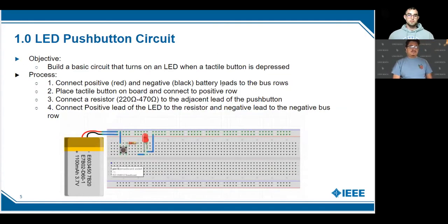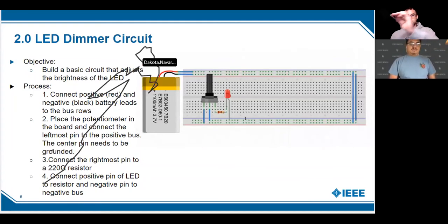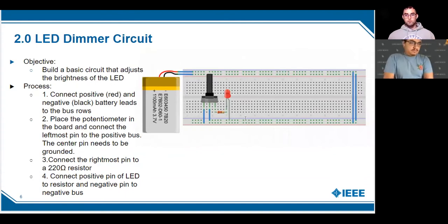One note I wanted to make is if you're using Fritzing and you build a circuit like this, Fritzing has a feature where you can test your circuit and it'll test all the connections for you. And that's really helpful for 201. You can build your circuit quicker on here and make sure you have all your connections to your IC chips correct before you go ahead and build it in real life. It's a little bit harder to troubleshoot in real life because then you have to use test voltage across certain components and make sure they're connected.